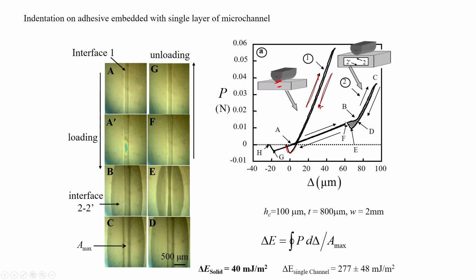The effective modulus is less because there is a thin skin here, and then this thin skin and the surface below contact over here. As a result, the modulus now increases, because it is the same material, and with further increase in load the modulus increases. So a similar displacement will now require more load to apply. Now, let us look at the unloading.